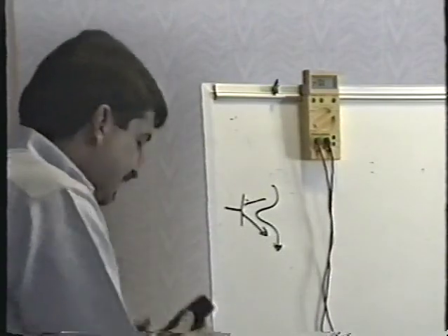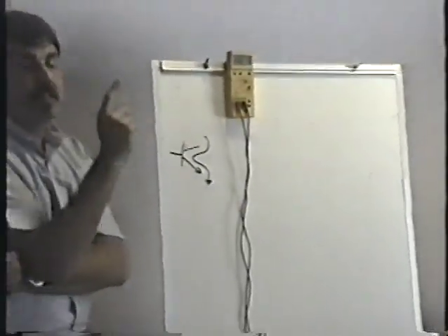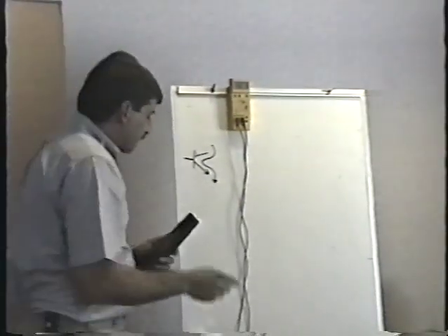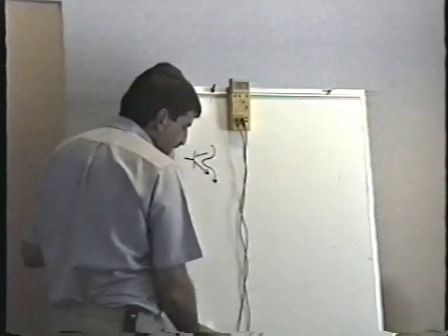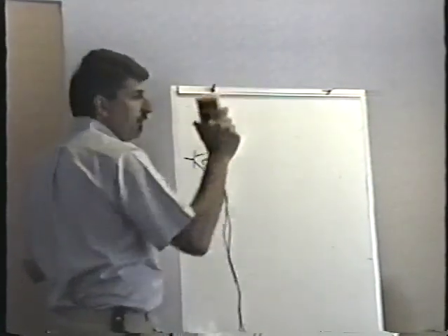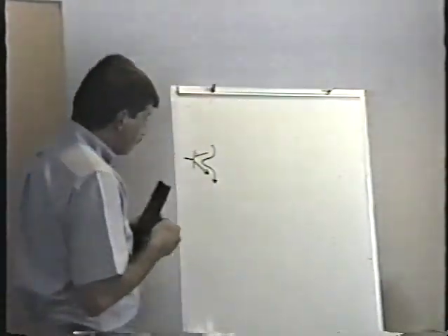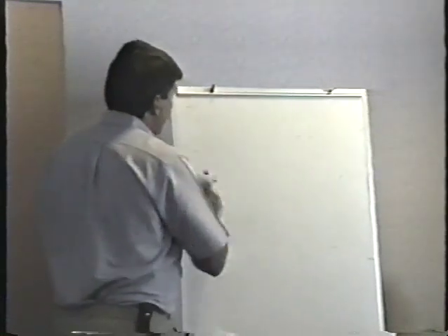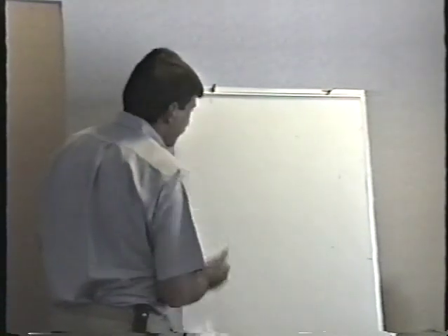Not only does this test tell you if the transistor is good or bad, but the test will also tell you if the transistor is an NPN or PNP. If you happen to have an unknown transistor and you want to know what the hell's going on with it, it'll tell you if it's NPN or PNP, the two opposite polarities.